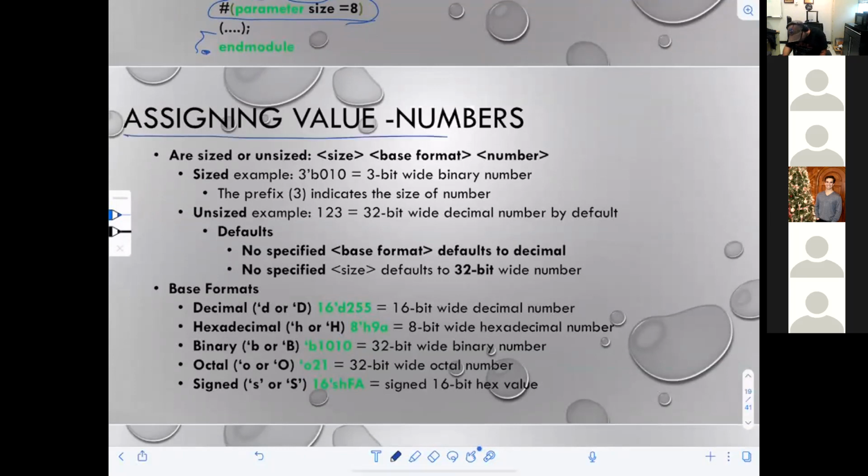Also, in the test bench, if you remember, I was using the decimal and I was using with you the binary, and there is other representation, right? Like octal, hexadecimal, whatever. So if I would like it to be hexa, I know it's 8-bit, it can be 2 characters. So that's why FF, like this, 2 characters. I have 16-bit, I would like to write them in hexa. So 16, H, and then there are 4: A, B, C, D. There are 4 because here's 4, 4, 4, 4, 16. That makes sense?